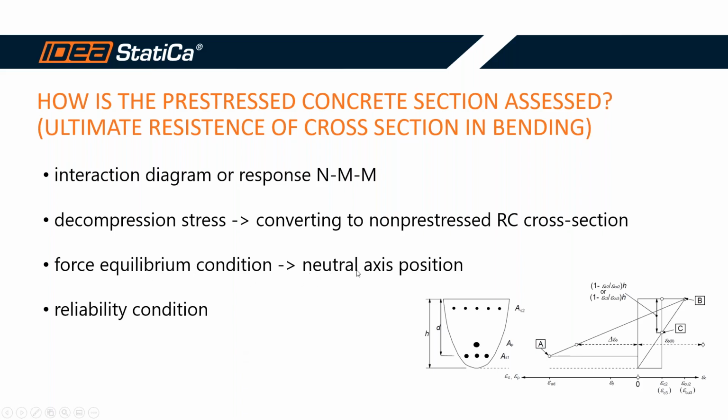From this equation we can get the position of the neutral axis, and once we know this plane of strain, we can check the reliability condition in moment resistance.